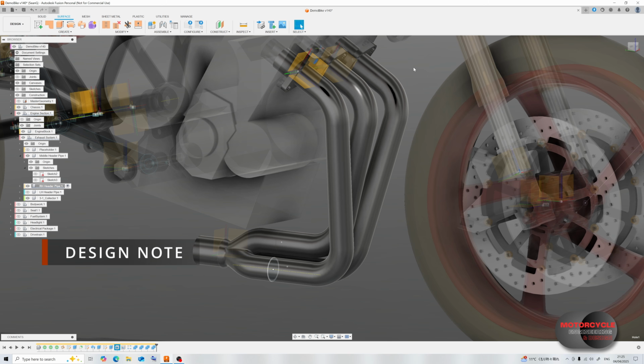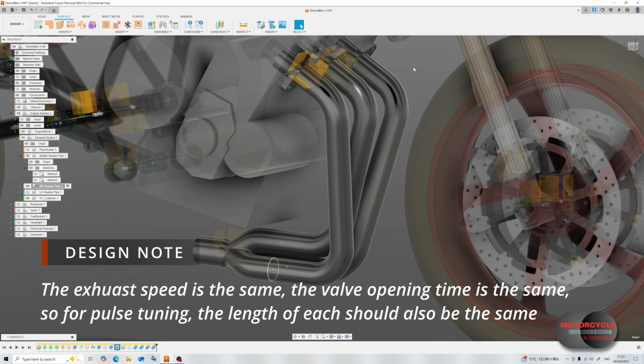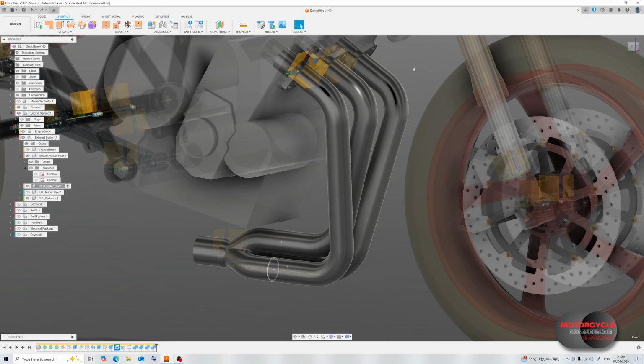They're going to have a slightly different firing order, but the exhaust gases are going to be traveling down these pipes. And when that gets to the expansion, that's where we get the pulse. And we want to tune it so that each cylinder is as efficient as can be at your selected rev range.